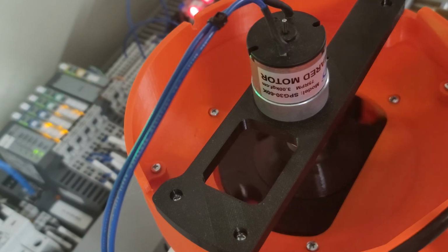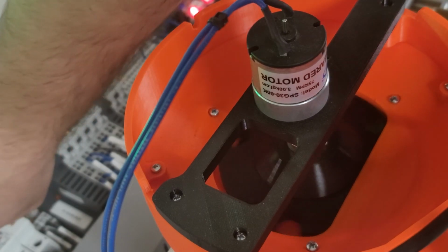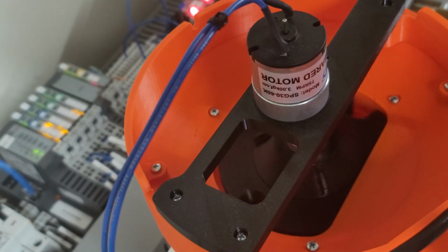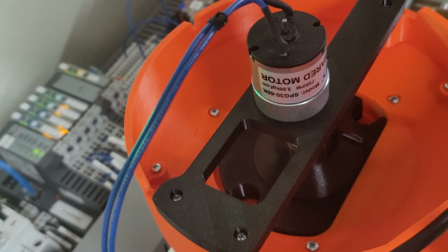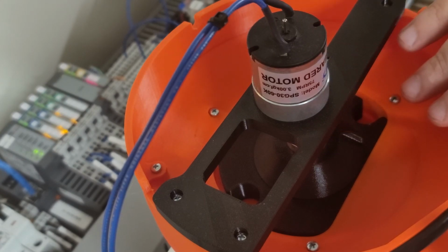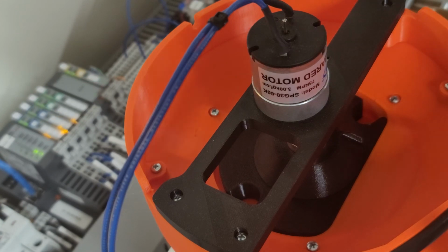So, as you can tell, it did a little bit of a ramp up. Now, it was kind of fast, so I'm going to stop it again. You can tell it had a bit of a ramp down, so that's a little bit better of a ramp down than what it was doing before, where it would just open the relay and it would just come to a stop naturally. So I'm going to increase the ramp up and down time to about 5 seconds, so that way you can see that the ramp up and ramp down are able to change more controlled.